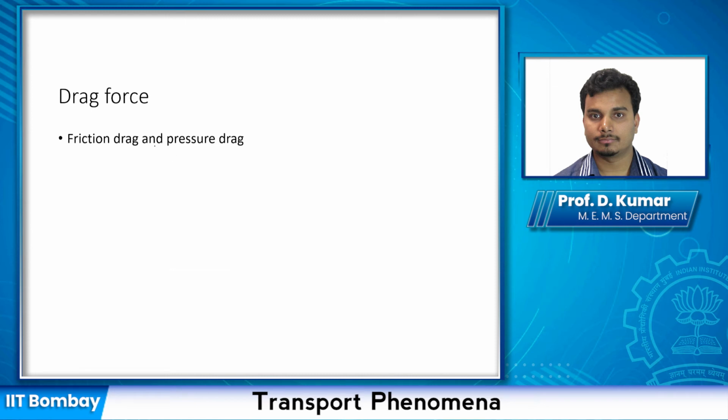Now we have seen, for external flow, we saw the flow over a flat plate, and in that flat plate we saw that it forms some sort of boundary layer here. This suddenly starts increasing. That is because of the interaction of this liquid with the solid. This is one type of interaction where flow is parallel to the surface. There is some interference to flow, because of this film formation. That is typically known as friction drag, where we have friction, relative motion between these surfaces. So you have some friction drag.